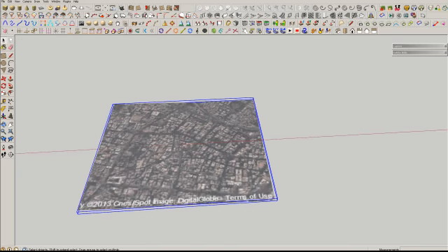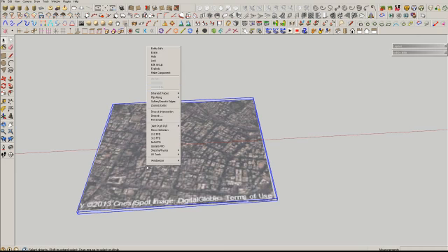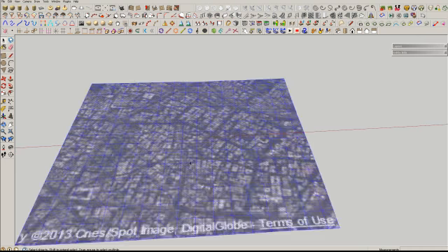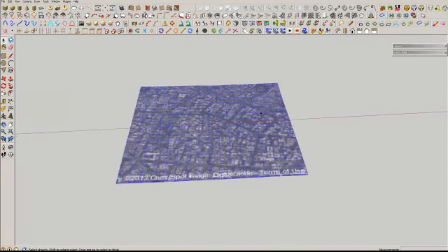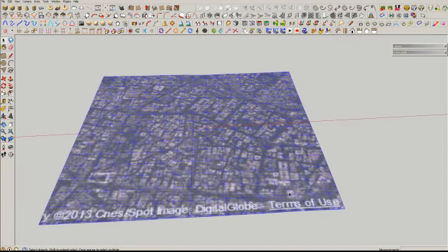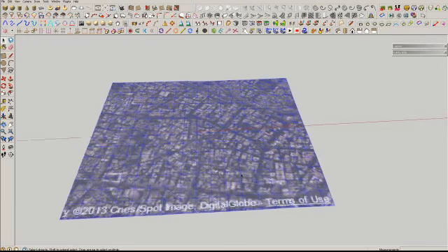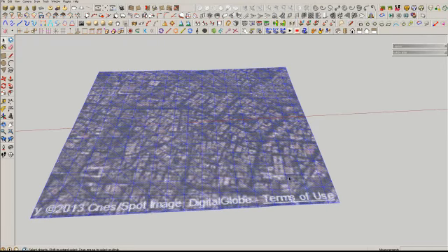Okay, now what you do is you select this one and then you right click and then click on explode, so that you get this whole thing as a surface, not as an object, right? Or as a component, you can say. It's something like creating an object in other software like Rhino or AutoCAD or anything else, right?